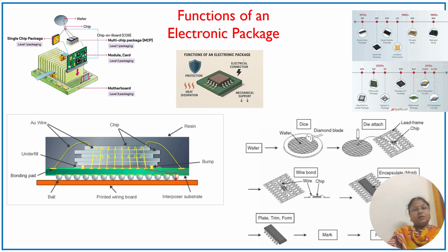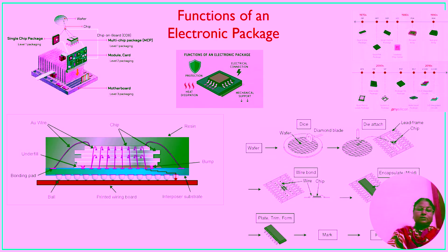So you can see the functionality in such a way of an electronic device. So this is an IC. For IC packaging, we have different types. Different vendors are going to provide you the IC and the packaged IC. It can be a dual in-line pack or a single in-line. So with packaging, how the leads are going to project outside is also our main concern.